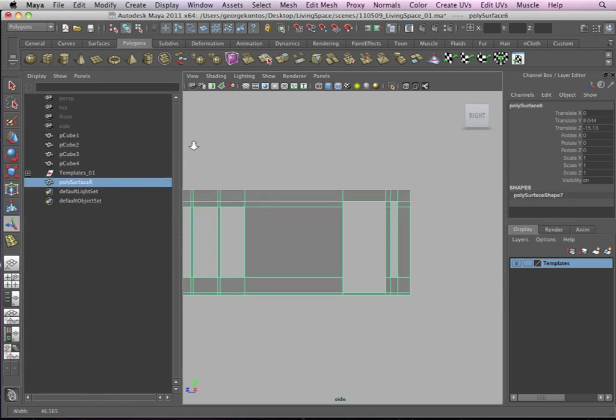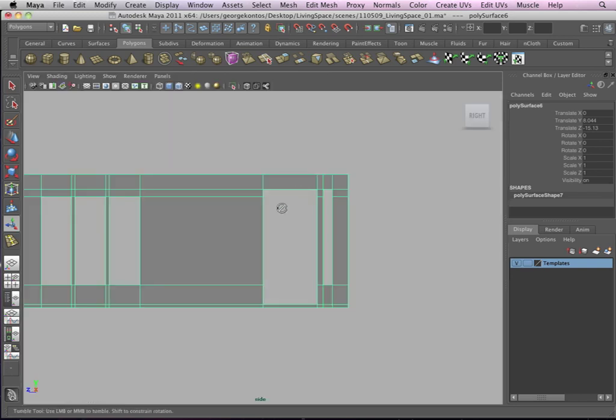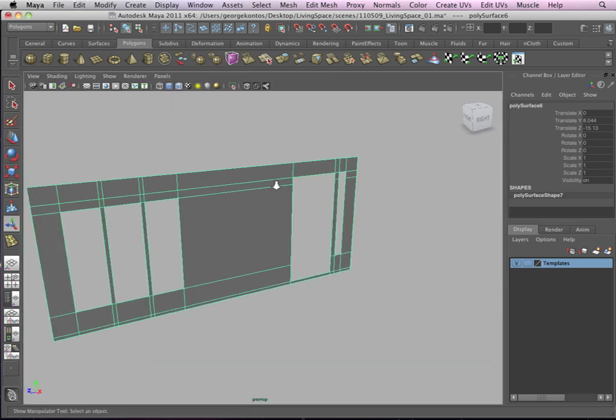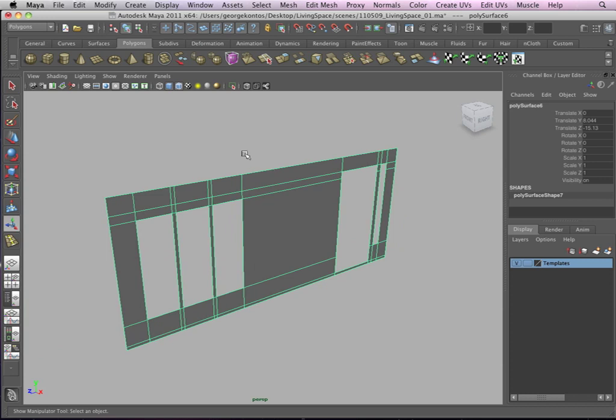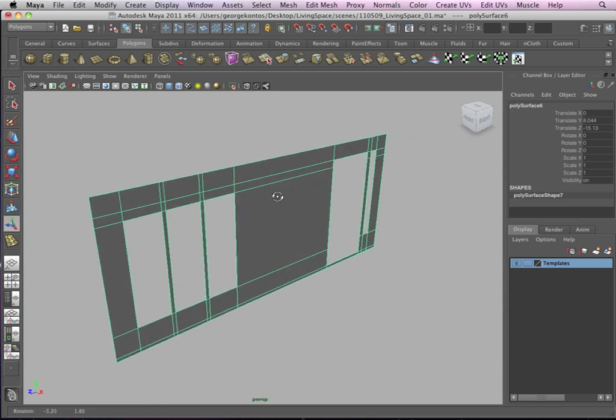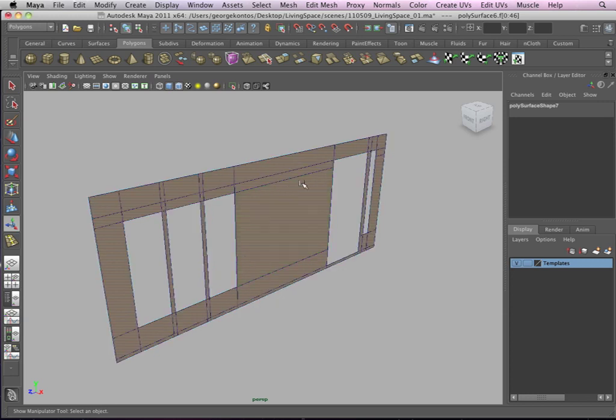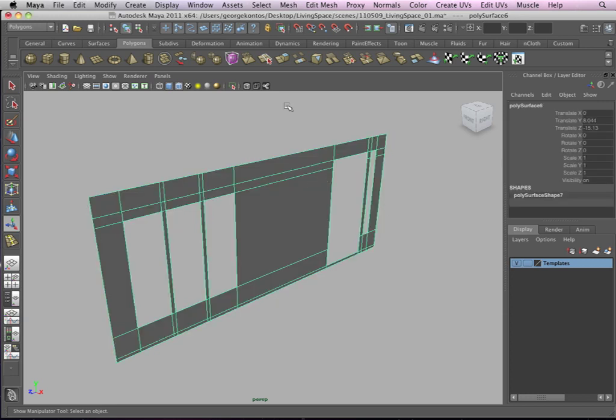This is my actual wall space. Okay, now I'm pretty much ready to extrude. So that kind of completes the first part. So I select the whole piece all together. I don't select the faces. I select the whole object because we want everything to be extruded.